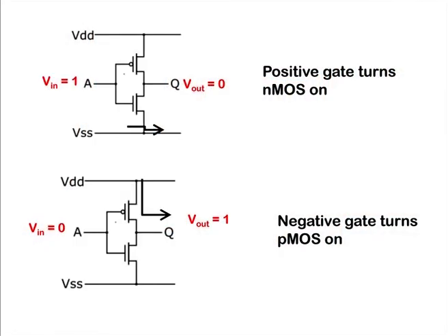Now I will come to the complementary metal oxide semiconductor. This one is the CMOS. Basically, CMOS is the combination of NMOS and PMOS. The NMOS we have to fabricate on a P substrate, and here the channel is the electron channel. In PMOS, the channel is the hole channel. Here you can see both fabricated together on the same device, and if you apply biasing, below you can see the circuit diagram.